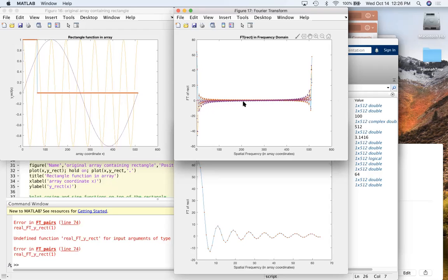Because I am doing a discrete Fourier transform, just by the nature of the fact that I'm representing my function with discrete points and taking a Fourier transform with a finite number of points, basically, I am in the sampled domain, right? So this is a sampled function now, and it has a delta X between sample points, right? Which is 1 over 512 or whatever.